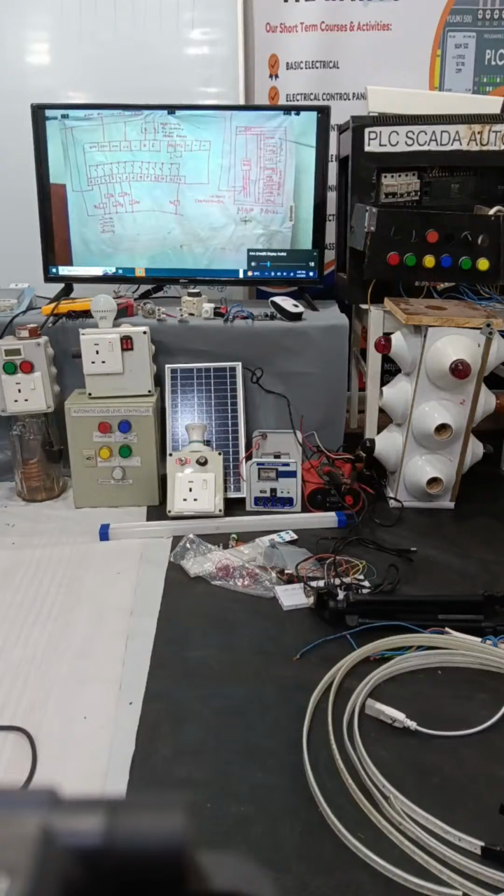So some loads like the blower and water pump are inductive loads. Depending upon the operation of these loads, the nature of the current is lagging because of the inductive load. These are the current transformers for metering of this panel, but there will be one fourth CT, current transformer.